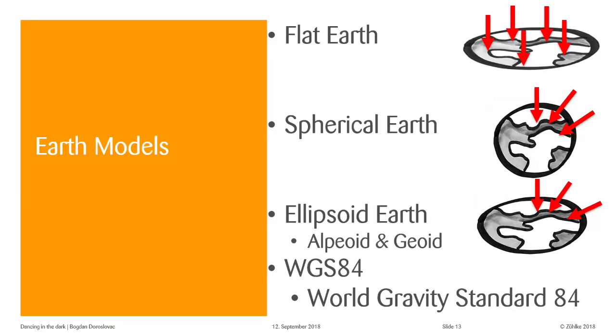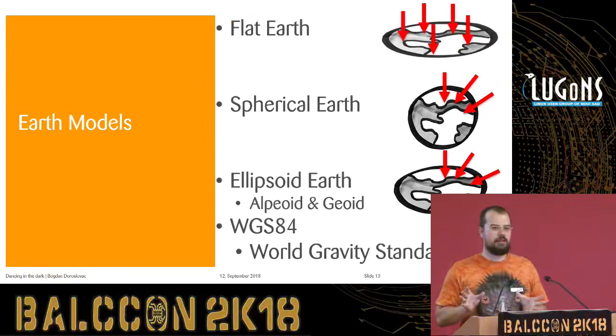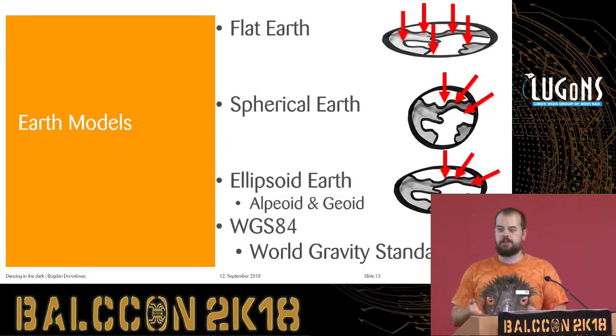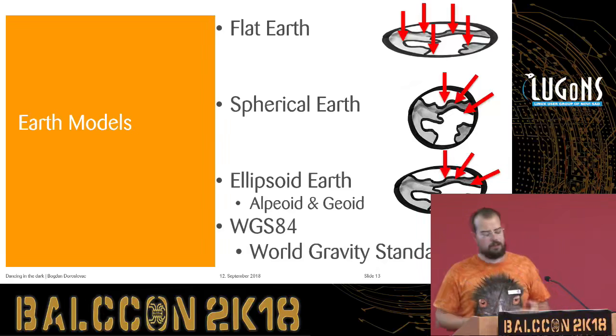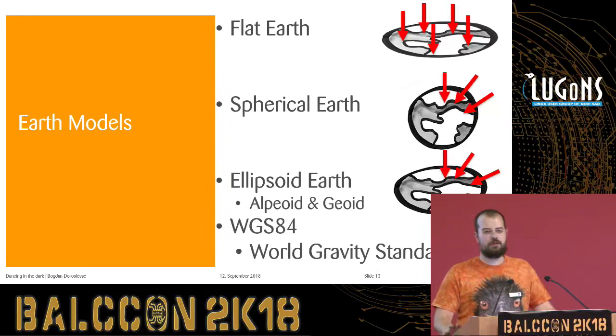And basically what it is, it's a referential ellipsoid with the gravity in all the possible places. So, like doing anything with the constants, don't be too smart about it. Go for this one. It's simple. You just punch in the latitude, longitude, altitude, and you basically get your effective gravity back. If you try to calculate, to compensate, to do anything, you will surely fail. You will be closely failing, but failing nonetheless.